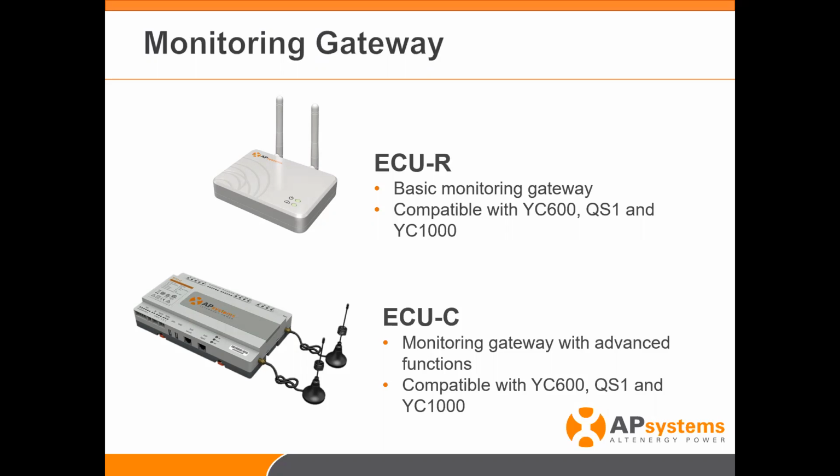That's the bottom line. And like I said, with the advent of the ECU-R and the use of Zigbee communication, we have literally reduced our phone calls by 50%. And that's huge. And I want to pay that forward to you guys, so you're not getting phone calls about internet connections. Like I said, I know it's not always possible. We do include Wi-Fi in both the ECU-R and ECU-C for those special cases or corner cases where you can't get an Ethernet connection. But nonetheless, Ethernet is the fastest, most reliable, most secure,